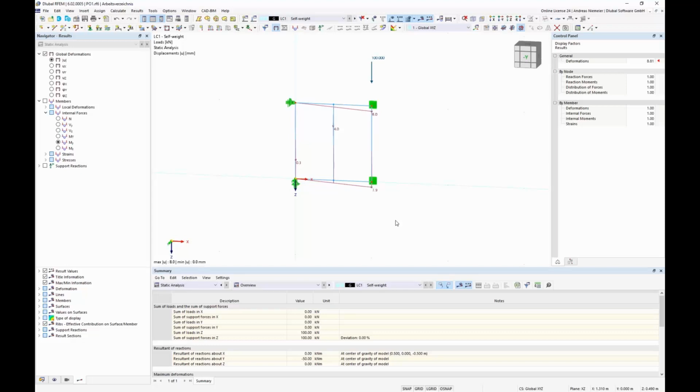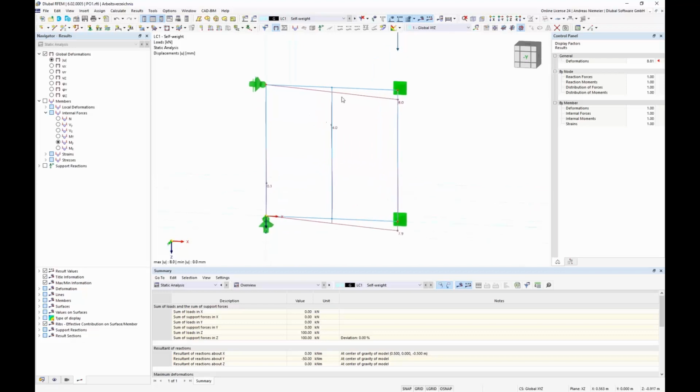And I would say now this is a job for RFEM, for the computer itself, and that RFEM can find a right place for this bracing. We have to give the computer the information what it can change to find the right place. And here it's clear for us we can maybe move this node in left direction or right direction here, and even here move the node in left or right direction.